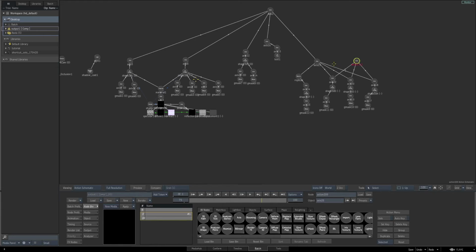I'm going to click and drag across the connection to those axes to break it, and then I'll drag off this main axis, the original main axis, from these geometries and feed that as a parent to our new axis we just created. This now gives us a control axis for our dial.